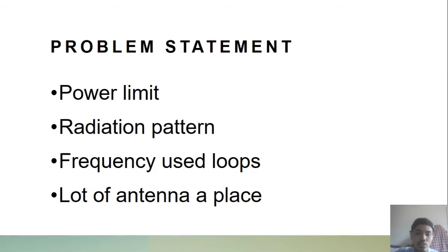Matching using a loading coil also generates a high voltage across the antenna ends. However, unlike the capacitor, the voltage change is gradual, spread across a physically long inductor and generally not troublesome.